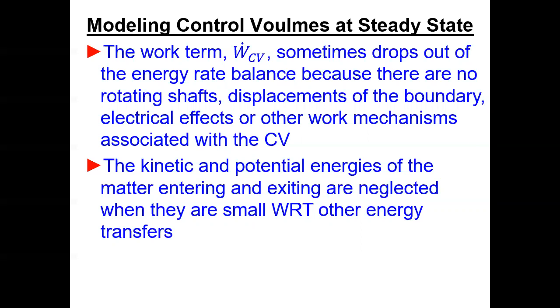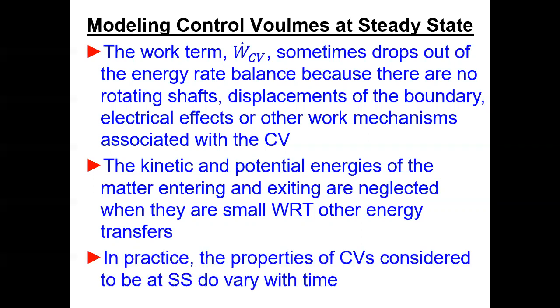Okay, the kinetic and potential energies of the matter entering and exiting are neglected when they are small with respect to other energy transfers. We almost always do that, though there are some problems already assigned to you where you have to include them. I don't know that we're including the potential energy term much, but the kinetic energy term, if you've got high flow rates of gases or things like that, then you have to include that kinetic energy term. So sometimes that gets included.